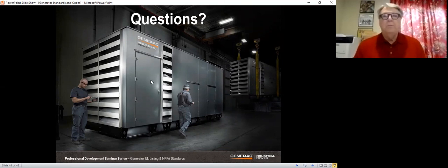And probably most important, the generator simply must meet NFPA 110 requirements. And that means it must have an NFPA 110 controller, and it must have all the proper sensors and so on to meet NFPA 110 requirements. If you require your generator to be UL, to meet all of the NEC emergency generator requirements, and to meet NFPA 110, you kind of covered your bases there, because they will fold into them a lot of these other things that I just have been mentioning.